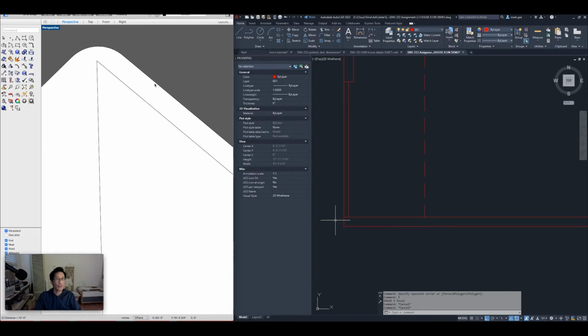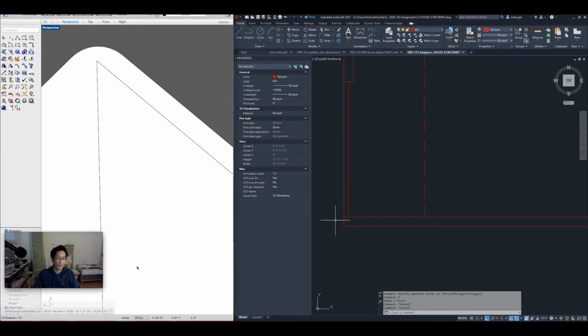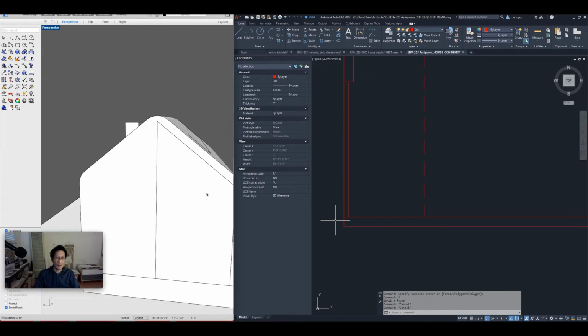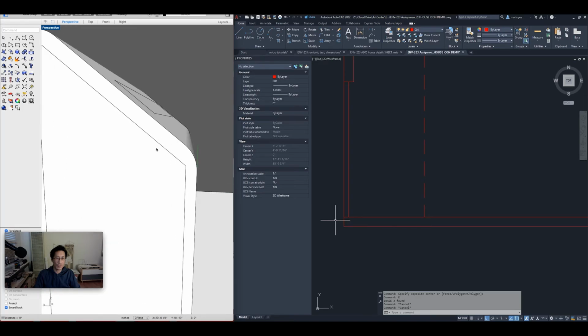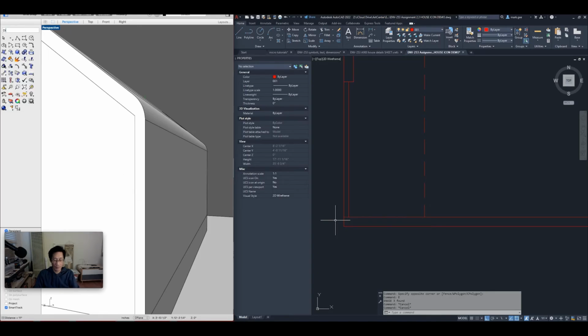Let's check the distance between these faces here, DI, or the lines. So here to the perpendicular is 11 inches. Move this up a little bit. And just to ensure that it's parallel, let's check it down here. Also DI from here to perpendicular, also 11 inches. And then let's check the thickness of this wall.